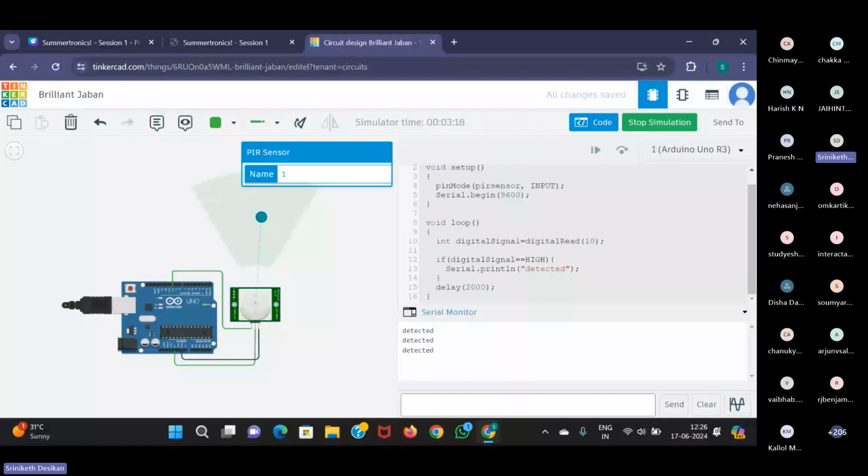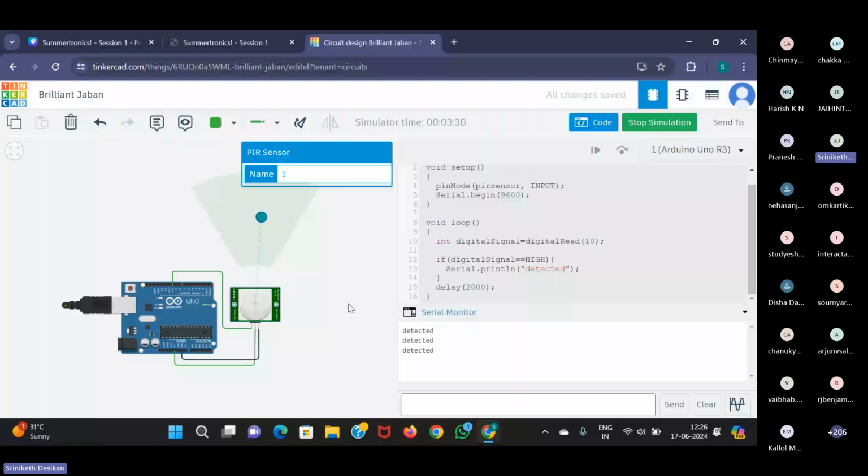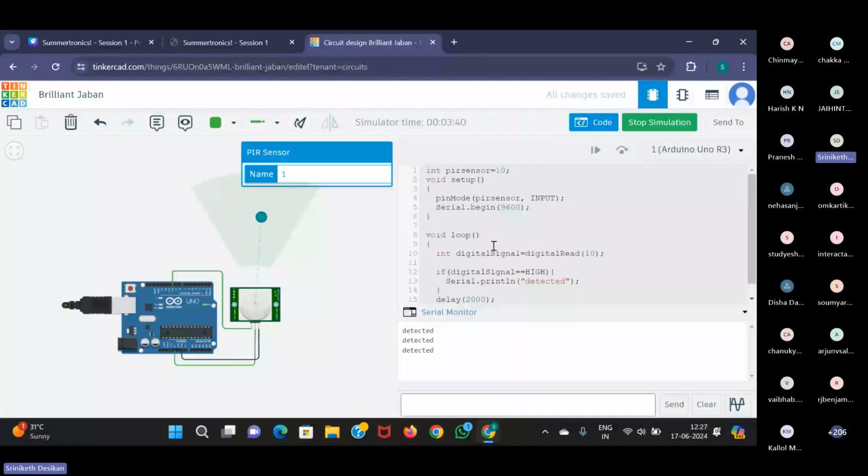Serial communication is between which two devices? Serial communication is between the Arduino and this IDE, this environment that I'm programming on and using to communicate with the Arduino. IDE is an integrated development environment, which is what I'm writing the program in. And both of these, basically, it's my computer. I'm using my computer to communicate with the Arduino, and the baud rate describes the rate of communication between these two devices. The serial monitor kind of acts as a middleman between the two, and we can see whatever we want to print as input output.